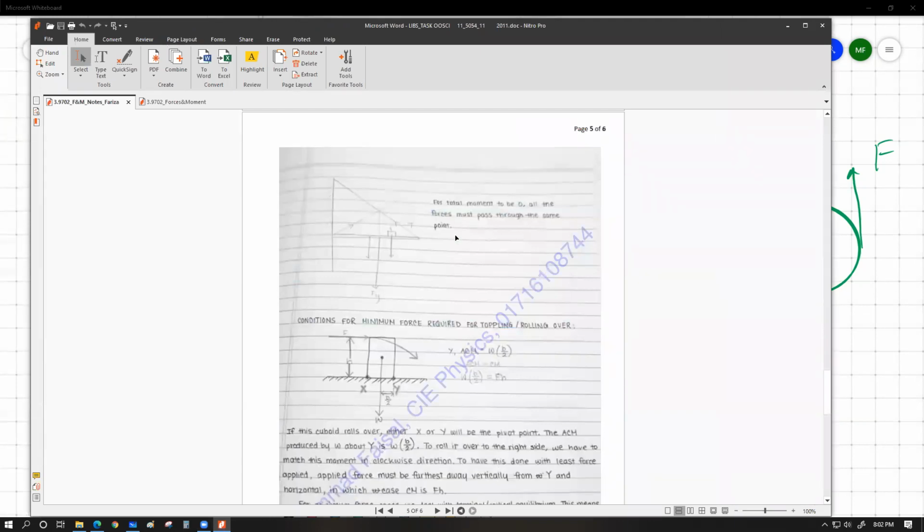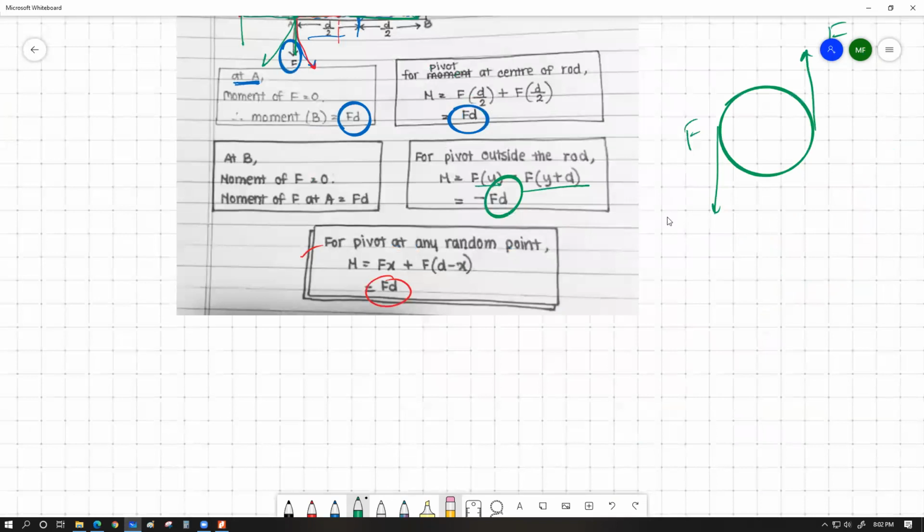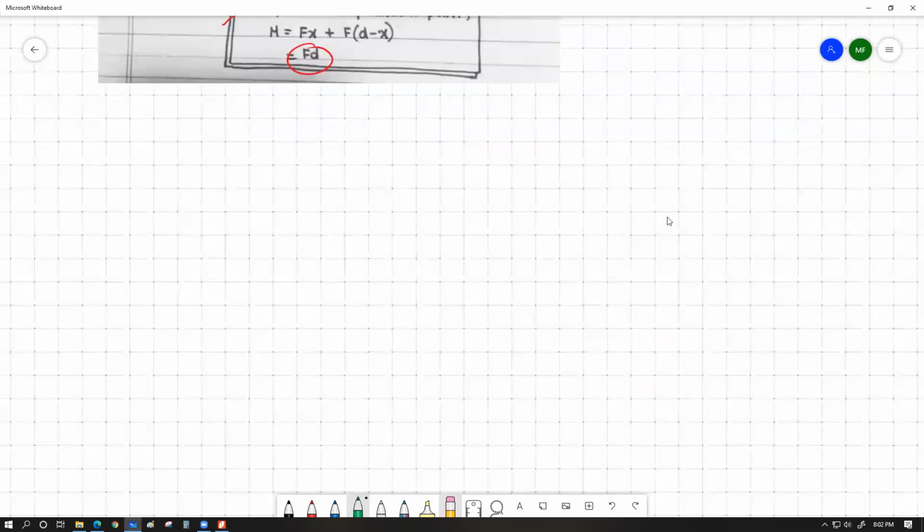Okay, the next thing that we have, let me draw the next part a bit. Whenever a certain object is considered to be in equilibrium, hear me out, we have two conditions. We can imply two conditions on that situation. For equilibrium of an object, first condition, resultant force should be zero, and second condition, resultant moment should be zero. We saw an implication of the resultant force being zero in the previous class: the vector diagram of all of those forces drawn with appropriate angle and appropriate scale should give us a closed polygon. That's a very simple way to put it.